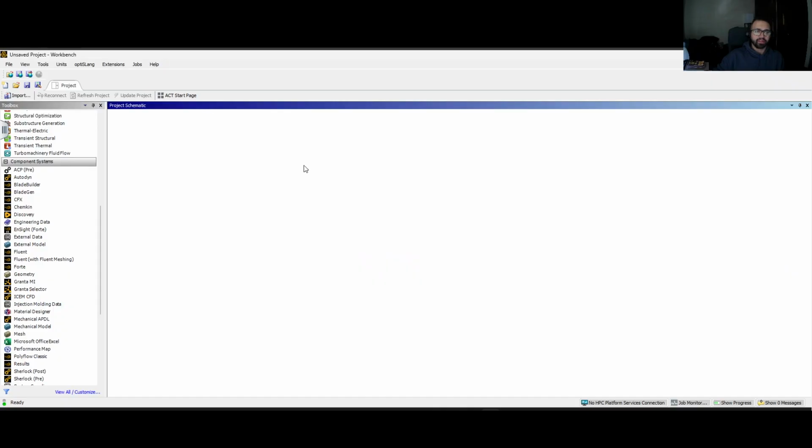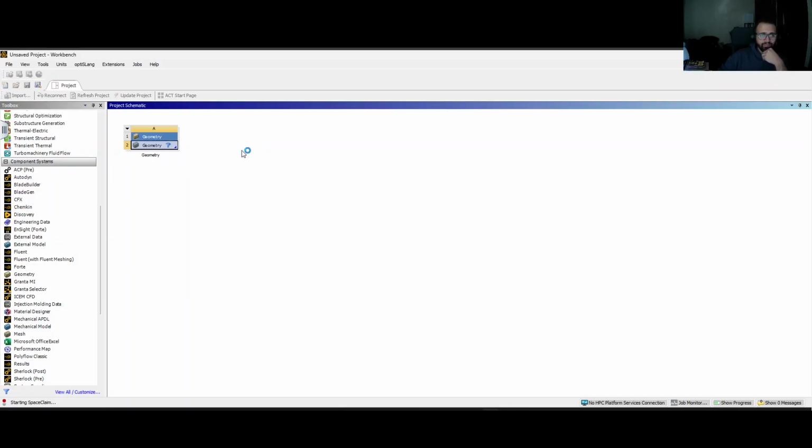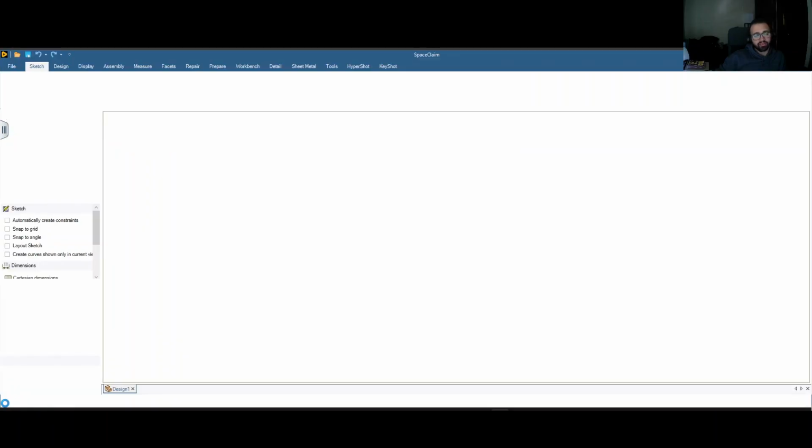Now let's move to Ansys. As most of you already know, this is the Ansys Workbench interface. We'll start by dragging the geometry interface, or you can just double click on it here. Now inside Ansys, there are multiple CAD modelers that you can use. By left click here, you can check which one is already the default. The one we will be using today is SpaceClaim. You can always keep an eye on the status of Workbench from this bottom left part.